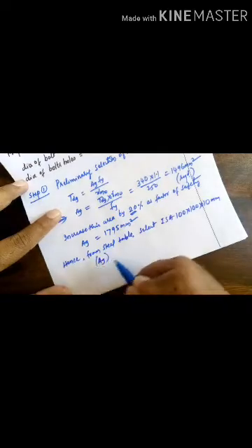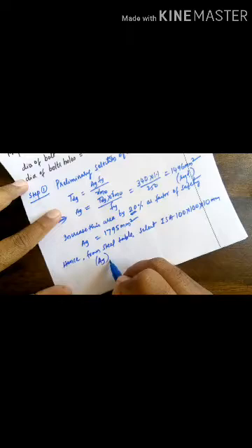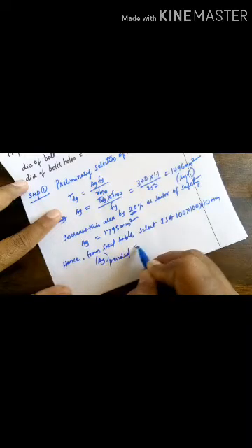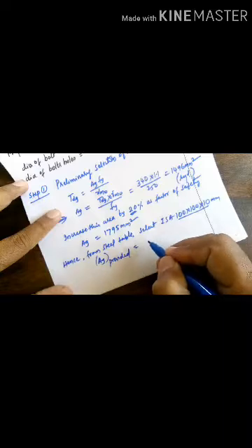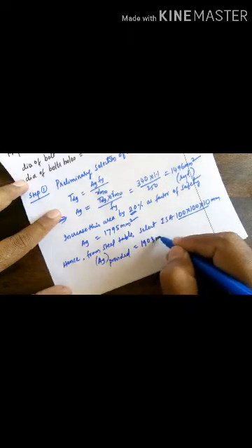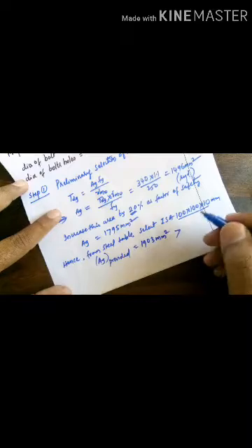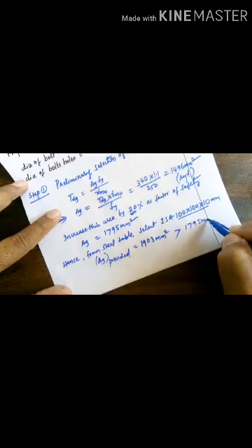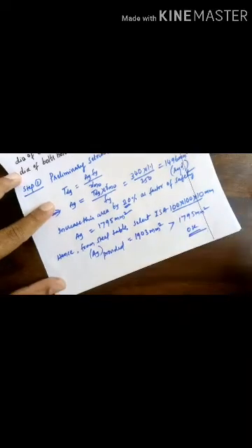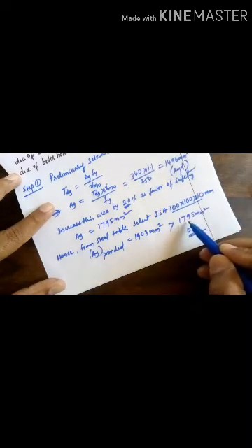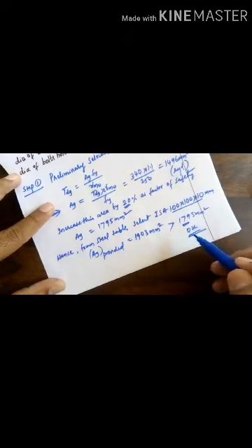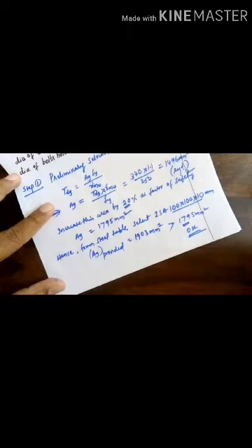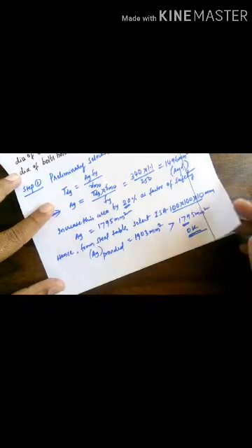So the area provided, for this angle we are choosing, will be 1903 millimeter square, which is more than 1795. So okay, or nearer equal to this much. If any section gives this much area, you can choose that section also, or else one more than that which is nearer to it.